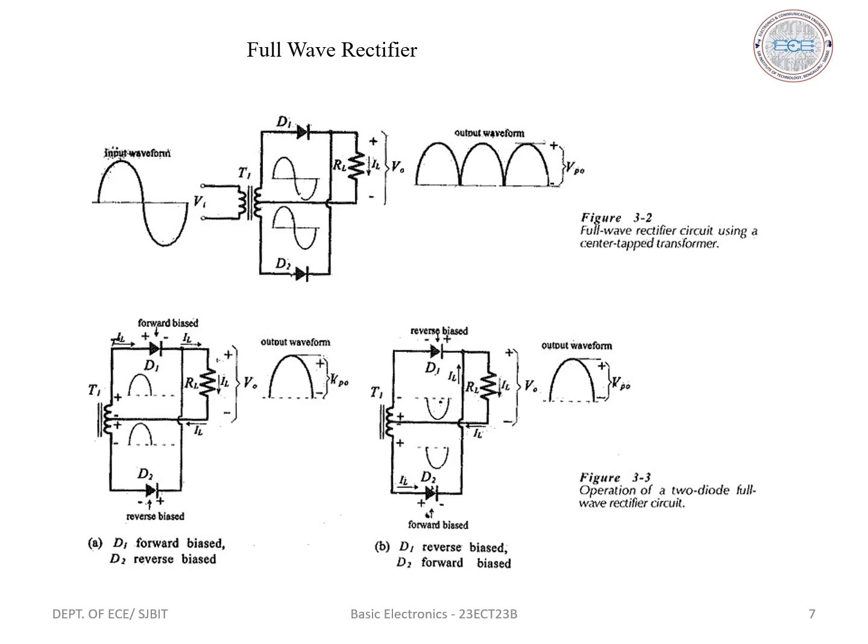During the negative half cycle, diode D2 is forward biased and diode D1 is reverse biased. Hence D2 is on and D1 is off. Therefore, the current flows through load resistor RL for both half cycles of input AC voltage.